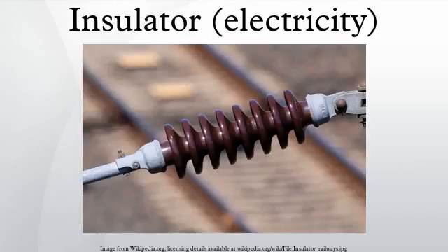A flashover arc is a breakdown in conduction of the air around or along the surface of the insulator, causing an arc along the outside of the insulator. They are usually designed to withstand this without damage. Flashover voltage is the voltage that causes a flashover arc. Most high-voltage insulators are designed with a lower flashover voltage than puncture voltage, so they flash over before they puncture, to avoid damage.